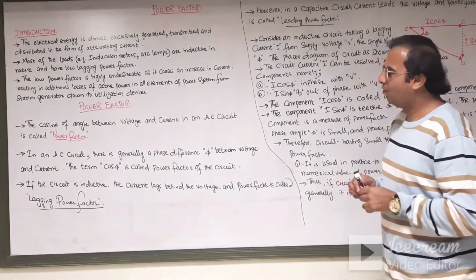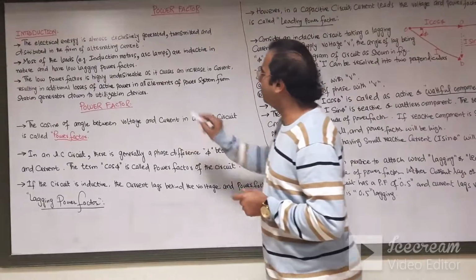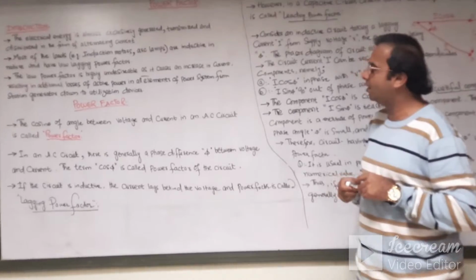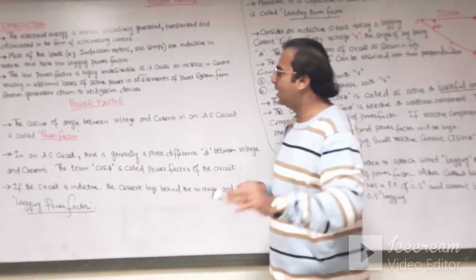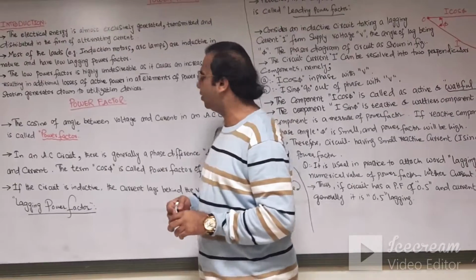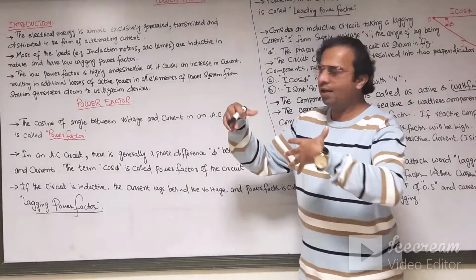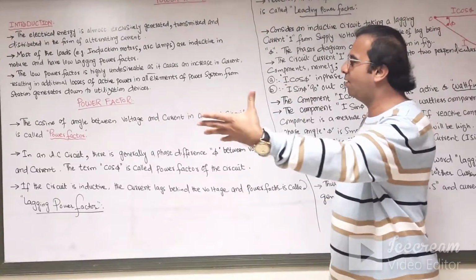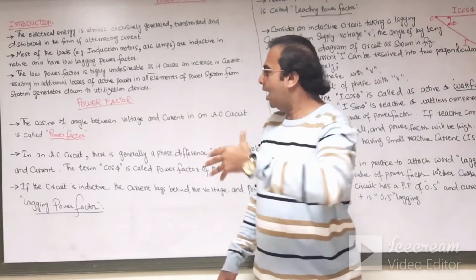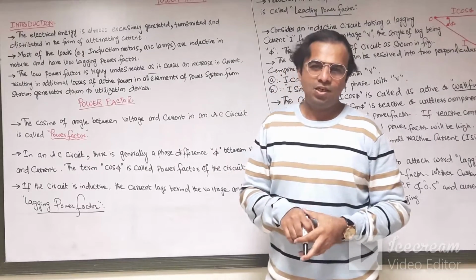The low lagging power factor is highly undesirable. It causes an increase in the current, resulting in additional losses of active power in all the elements, starting from the power station generator up to the utilization devices.